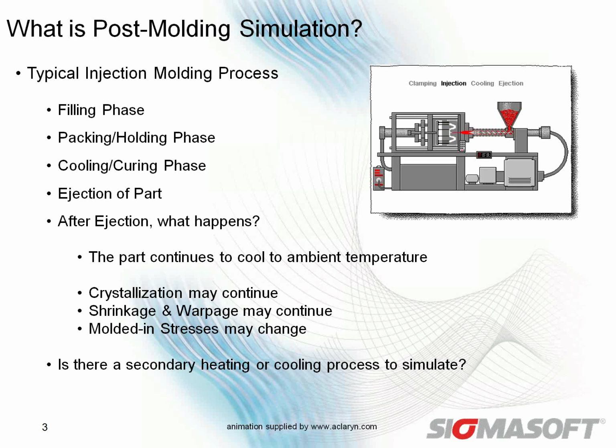Every polymer has an ejection temperature, so we want to reach some temperature at which we can eject that part. Typically, it's still hot when we eject it because we want the shortest cycle time possible. Even if you have some thicker sections, if you actually cut that part open, some of those thick areas inside would be really warm. And that's the goal here today: what happens after ejection.